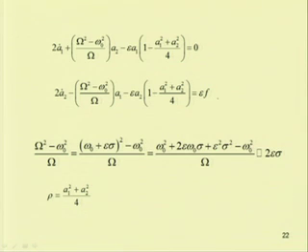So, these two equations can be written as 2a₁ dot plus (ω² minus ω₀²) by ω into a₂ minus εa₁ into (1 minus (a₁² plus a₂²) by 4) equal to 0, and the second equation becomes 2a₂ dot minus (ω² minus ω₀²) by ω into a₁ minus εa₂ into (1 minus (a₁² plus a₂²) by 4) equal to εf.